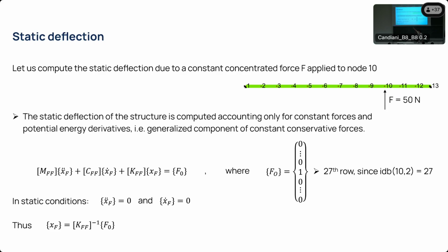So in a way, we could say that the first derivative of the displacement field due to an external load will be 0, and the second derivative, of course, will be 0, so no acceleration due to shifts in gravity. So we are left with a stiffness matrix of our system in free coordinates, because remember that the frame coordinates do not move if you apply an external load, and if they move, that's a bigger problem than finite element analysis.